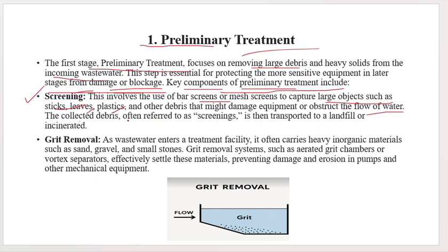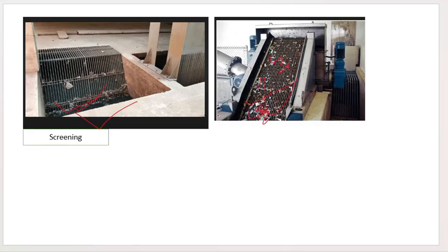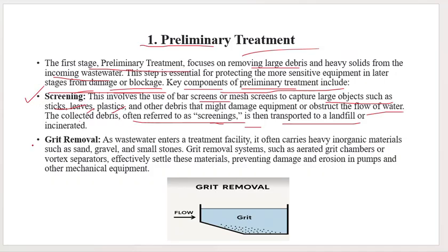The debris collected by screening, often referred to as screenings, is then transferred to landfill or incineration. After collecting, these solid materials are kept separately, then sent to landfill or other treatment processes. Okay, and now to grit removal.